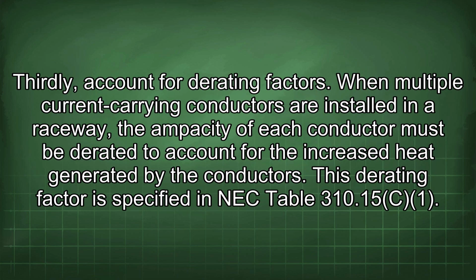Thirdly, account for derating factors. When multiple current-carrying conductors are installed in a raceway, the ampacity of each conductor must be derated to account for the increased heat generated by the conductors. This derating factor is specified in NEC Table 310.15.